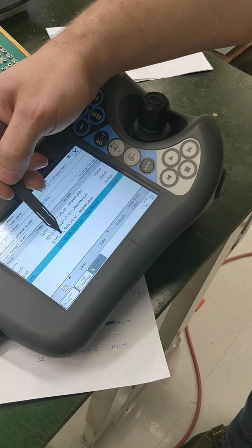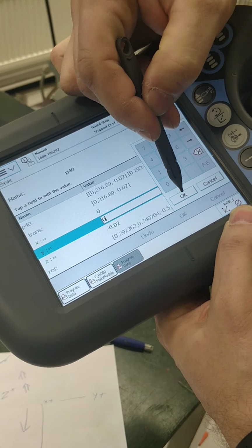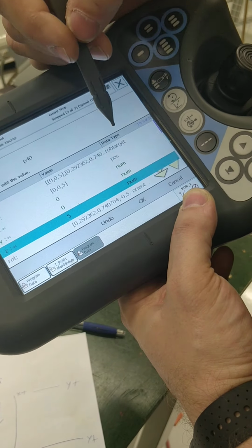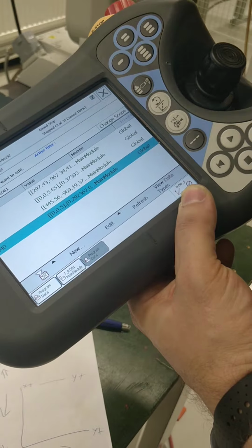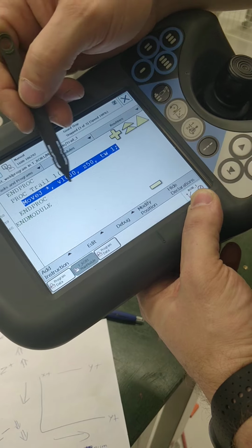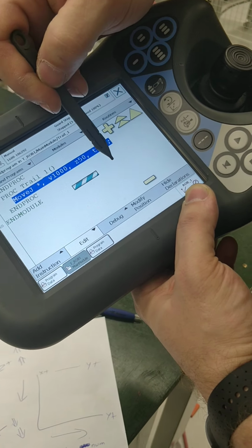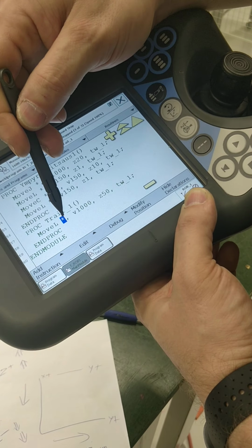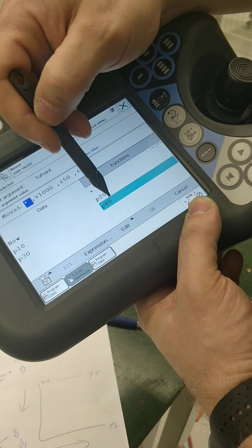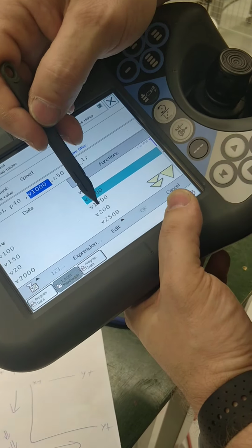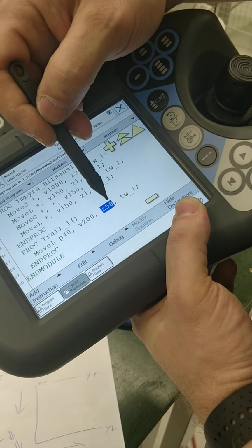And if I put that position P40, I go there and pick that also back to 0, but I lift up that robot a little bit. I pick here that okay, it should be 5 millimeters. And okay. And now I go to my program. And there is a move J. I pick that one and change it to move L. That should now be the move L. Then I pick that one, and I go there and pick that P40. Okay. And I also put that a little bit lower. Then I put the fine.